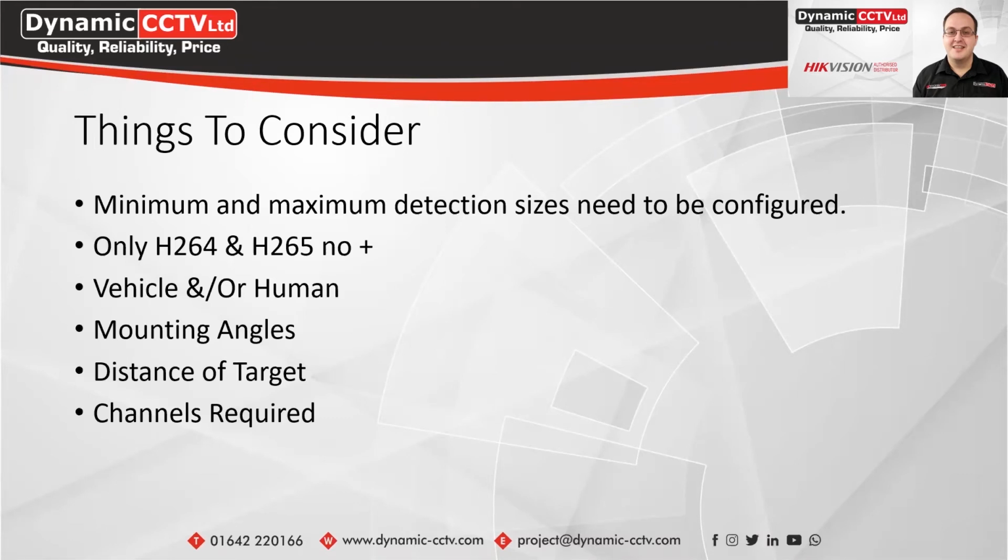You also need to consider the actual distance of the target, so where you actually want to be able to pick up the person or the vehicle with the line crossing or intrusion detection. If it's at a greater distance, then you could need a bigger lens or a varifocal lens, which makes it easier to actually focus the camera on the area that you want it to be for coverage, and then you can set up your analytics as you want to.